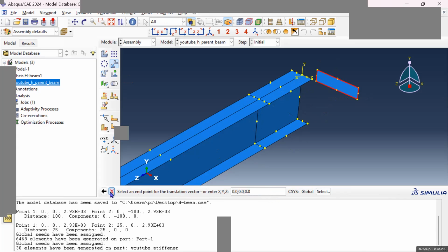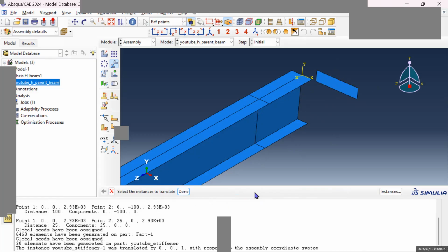No, hold on first. Let me restart. You have to select it first. Click here. The first one should be 0, and the next I need to go from 0 to 1. 1 means it should rotate only in the Z direction. I'm going to click on OK. It should be 90 degrees. Position of instance, OK.